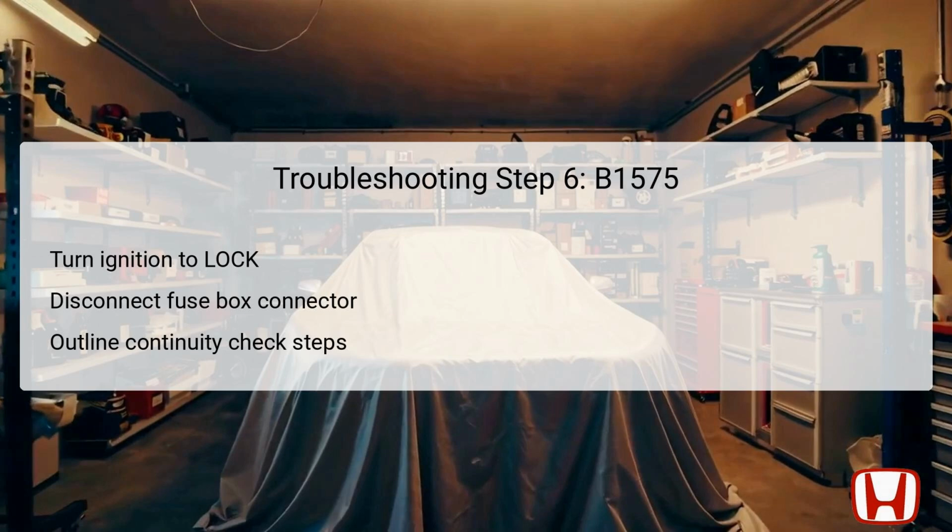the two connectors. Checking continuity between the passenger's under-dash fuse relay box connector D, terminal number 9, and the automatic lighting sunlight sensor 5P connector, terminal number 1, is essential to identify the health of the wiring leading to the sensor. A continuity test will allow technicians to determine if there are any breaks in the wiring or issues leading to high resistance that could be affecting sensor performance.